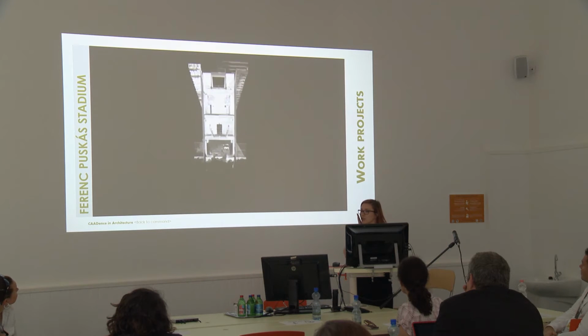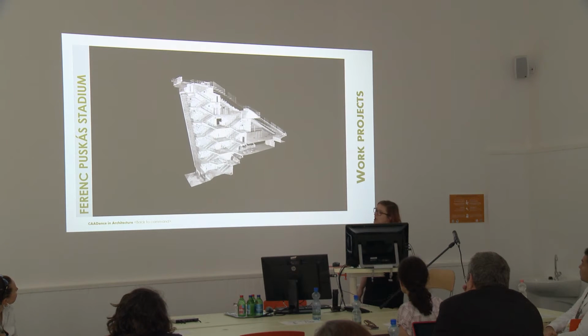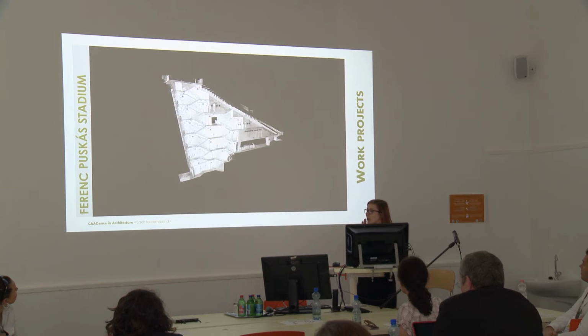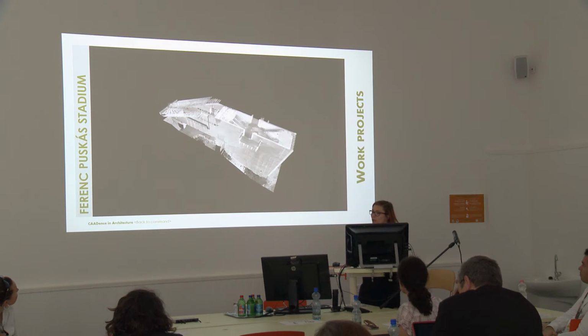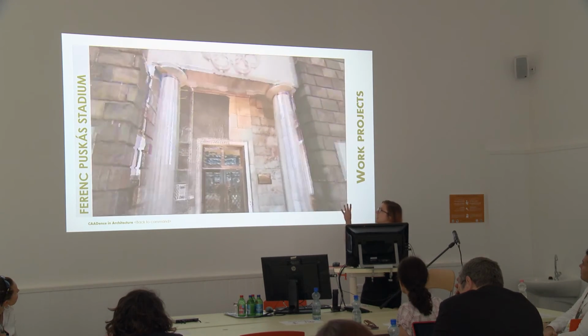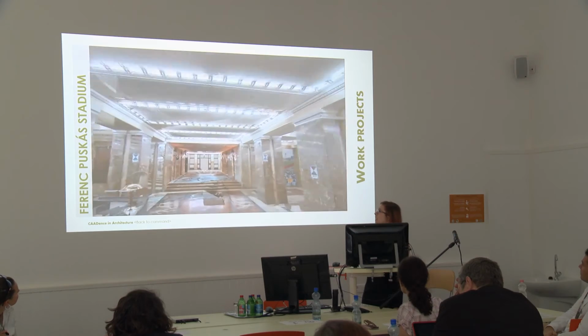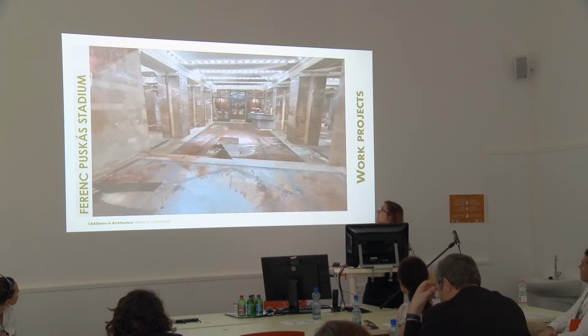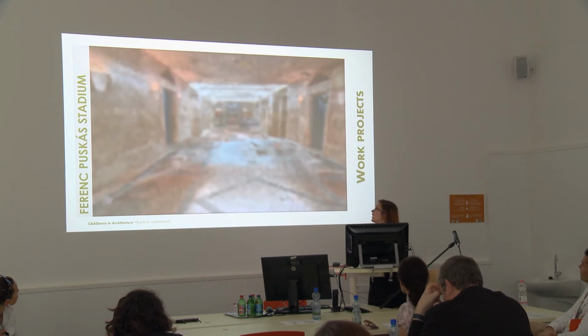And the 2 individual datasets were combined with physical control points, which were surveyed by total station also. Here you can see one part of the stadium where we took panoramic images. This is the RGB colored point cloud.